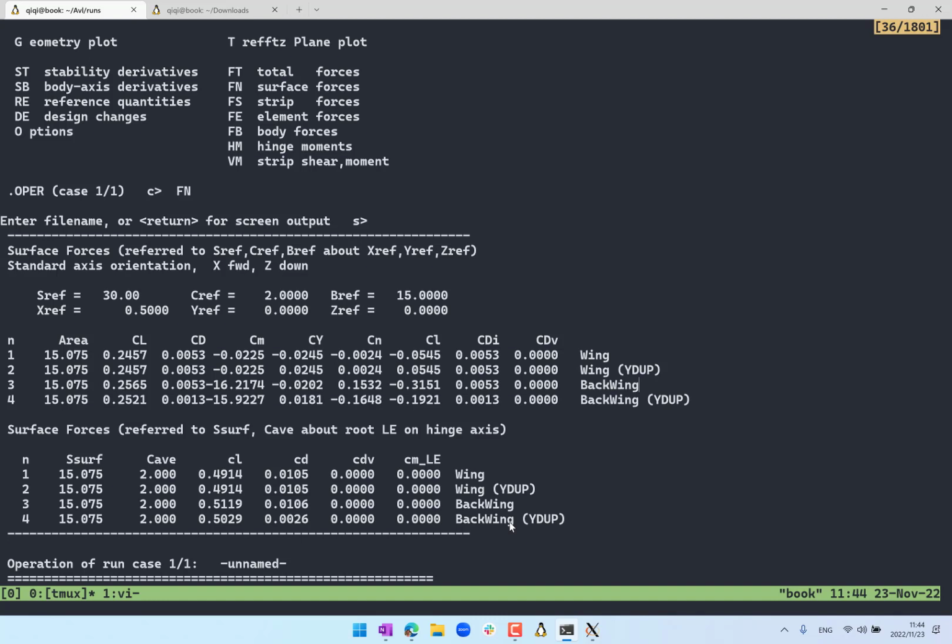Induced drag on each side of the wing. Oh yeah, that's the job of the vertical tail, right? If you account for the detailed flight, if you fly a glider, by the way, I don't know if you do flight simulations, the Microsoft Flight Simulator just released two gliders, and you can try flying them. If you actually fly a glider, somebody is towing you, and if you want to offset a little bit to one side, the towing force is also a vector. What do you have to do if you want to offset to one side? You actually have to bank a little bit, so that the thrust force coming from the tow line is balanced. Let's say you want to offset to the left, then the tow line is going to tow you towards the right. So you have to bank left a little bit to offset that.